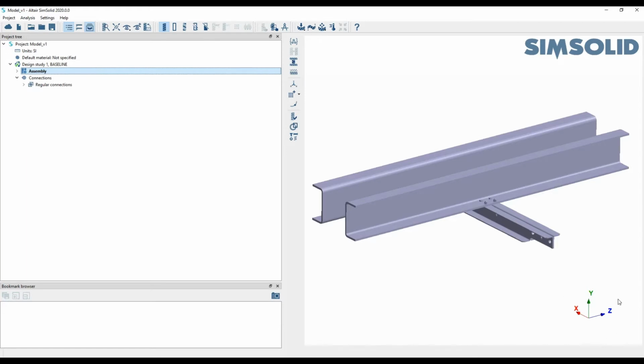So by default, obviously you know that this is our global axis, but should you need to create any sort of user-defined coordinate systems for local axis systems, you can. We have what we call spots, so you'll see that when we do select a face, occasionally for this whole beam say itself, you can select the whole face, but say if you only wanted to apply pressure on a certain area, with spots itself what you can do is make sure that you draw a square or implement a sort of section area where you want to implement your boundary conditions onto. We can go through that in the example later when we set it up for a linear static analysis.